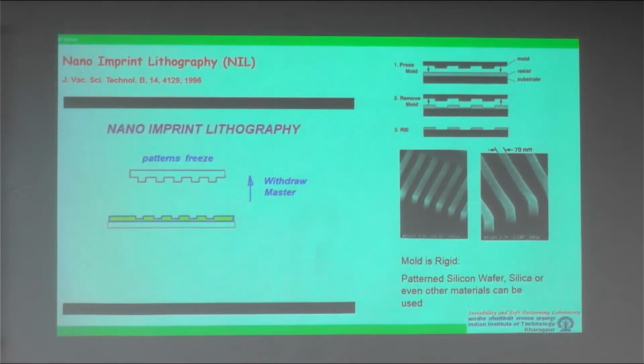The only thing that might differ from material to material is the exact value of the glass transition temperature. Even for the same polymer, depending on the molecular weight or the chain length, the glass transition temperature may vary. Because if you have a longer chain polymer, you probably will understand the effect of entanglement will be higher, and therefore you will need to supply more energy to make it soft.